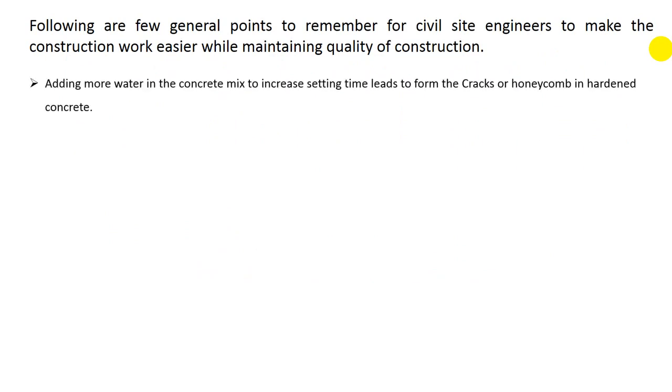Adding more water in the concrete mix to increase setting time leads to cracks and honeycombing in hardened concrete. Adding more water in the concrete mix is not good for setting time and also not good for hardening of that concrete.